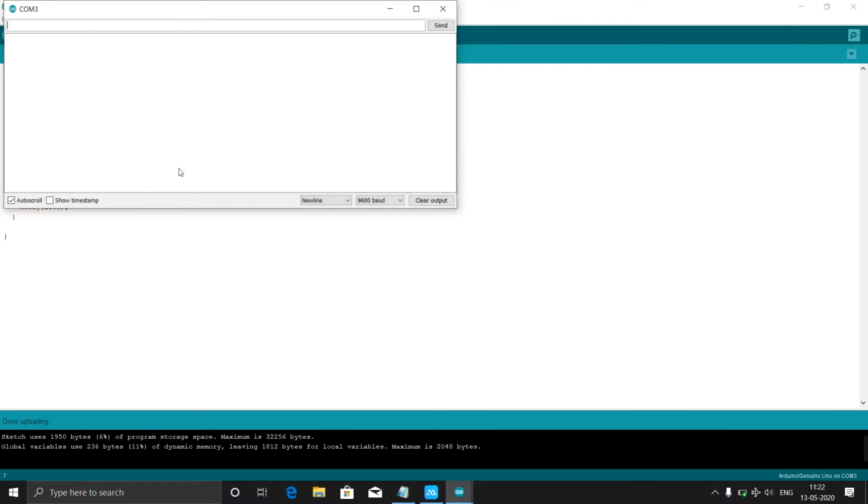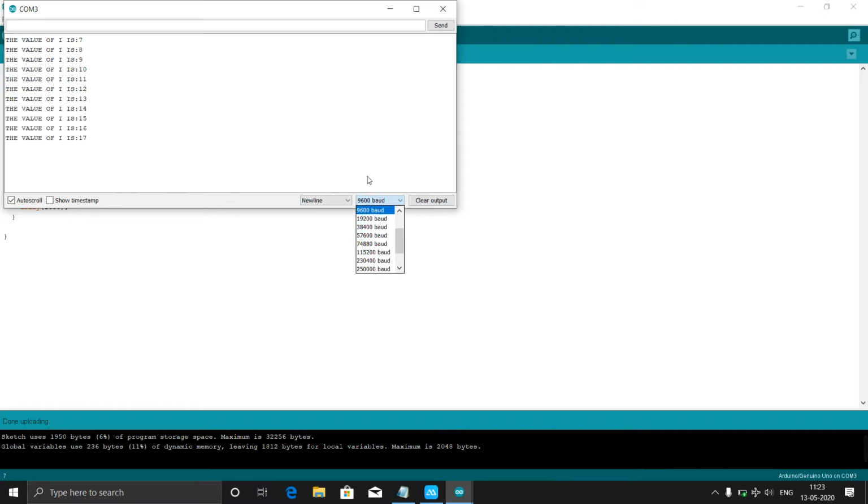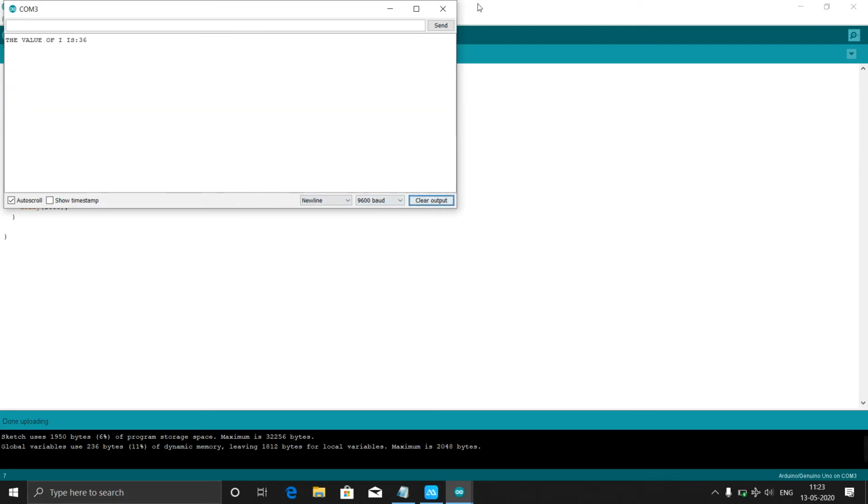Yeah, here, hi, I'm learning Arduino, you can see this. And here the clear output option is also there, it will clear all the things. And here what I told is the baud rate, that is 9600, 115200, 19200. For example, some devices transfer the data at some baud rate; this 9600 we can use generally, but for example if we consider some GSM modules that transfer data at the 19200 baud rate, for that it is helpful, that I will tell. Okay, clear output we can do.